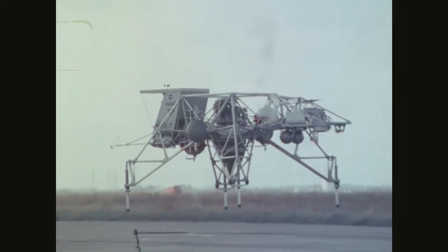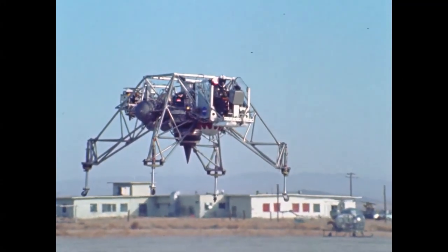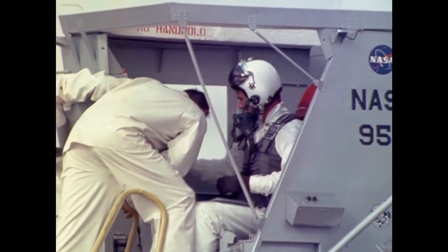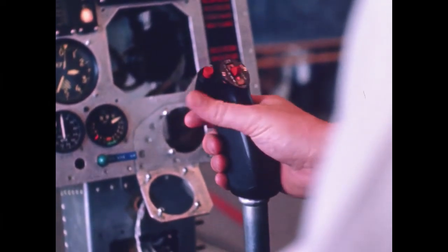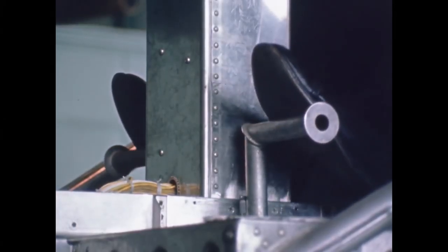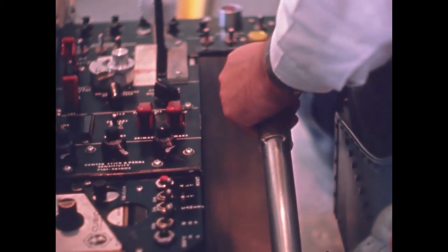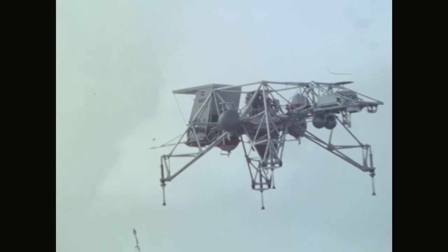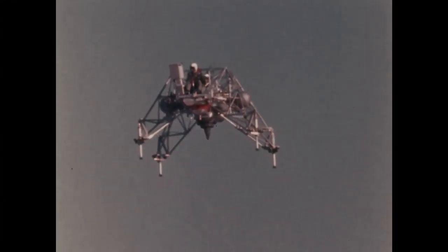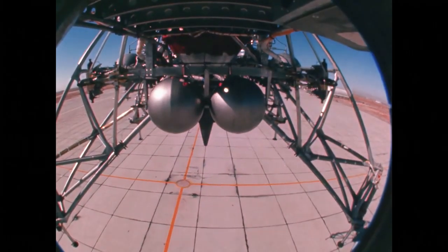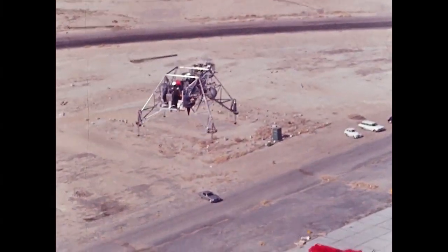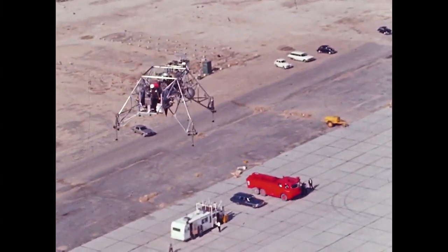And so the Lunar Landing Training Vehicle, or LLTV, was born. It featured a partially enclosed cockpit with LEM-like visibility, a 3-axis control-mounted side stick, a lift rocket throttle replacing the collective, and LEM displays, with a rate command attitude hold system that closely approximated the expected lunar module performance. The LLTV proved to be an excellent simulator and was highly regarded by the Apollo lunar module crews as necessary to lunar landing preparation.